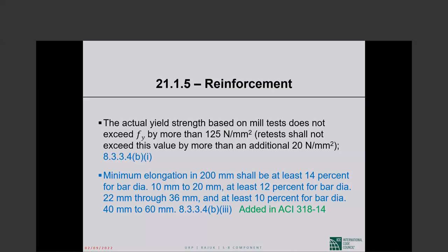Quite often, it is not. And that came up with the load combinations with overstrength factor yesterday. You just cannot use it when you like and make members stronger. That may very well be to the detriment of your structure.